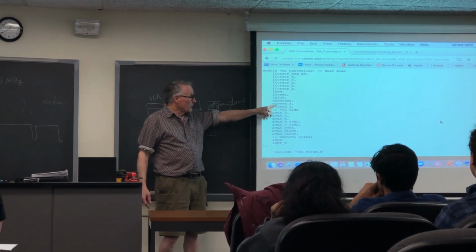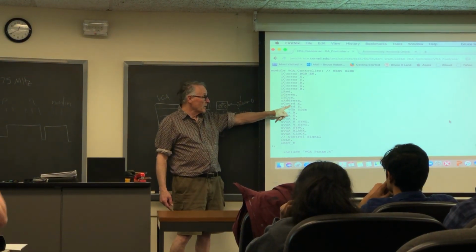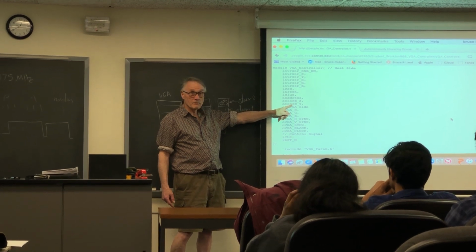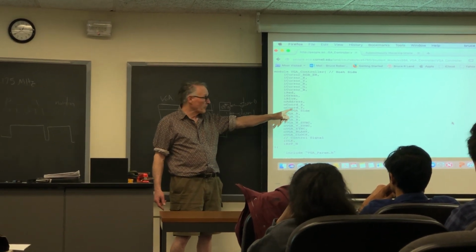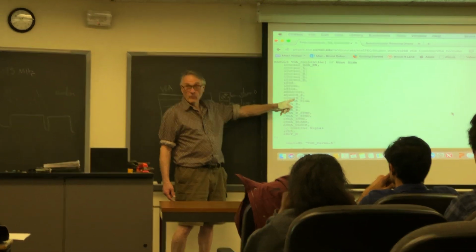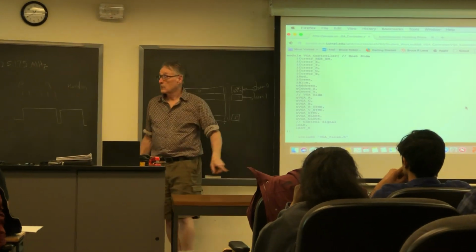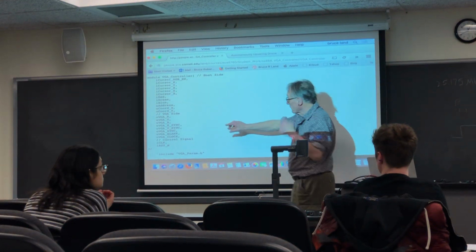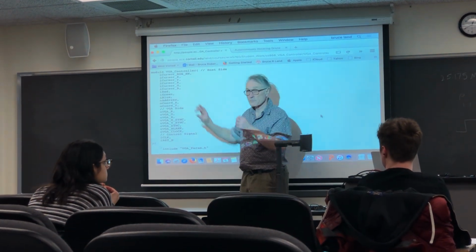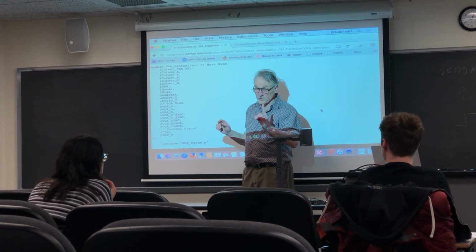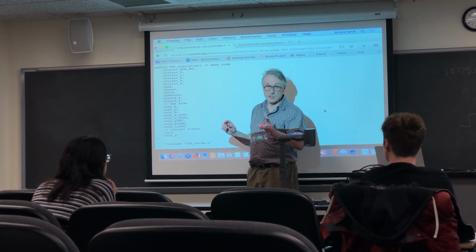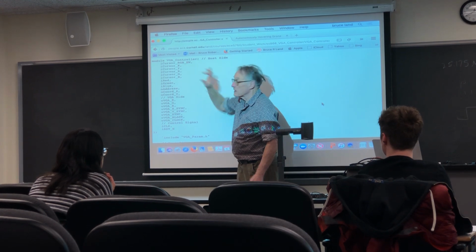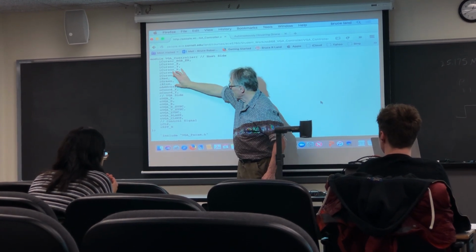The memory pointed to by either address or concatenated coordinate X and coordinate Y, depending on whether you like to think linearly or in XY coordinates. So this module, the VGA controller, is going to produce an address. 1 or 2 cycles later, and that's a parameter you get to choose, back out of memory comes a color, which goes into these 3 inputs.